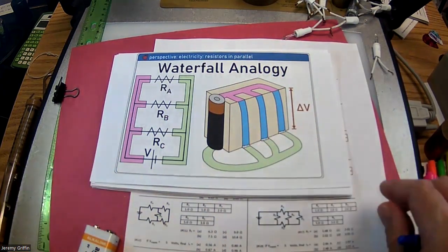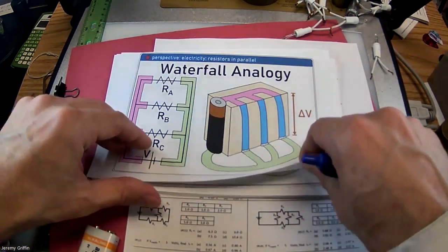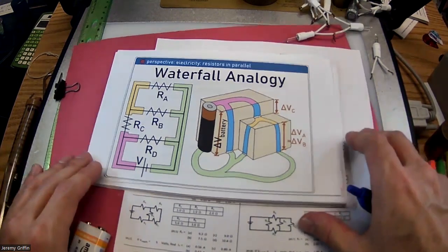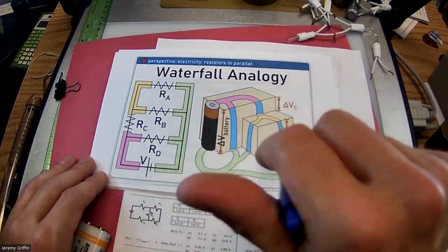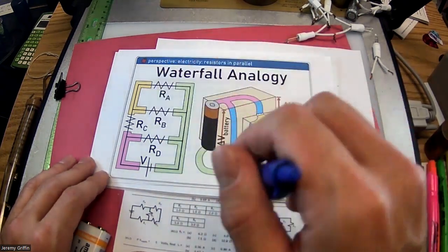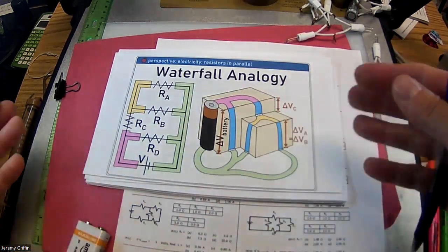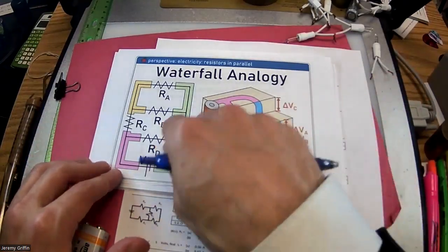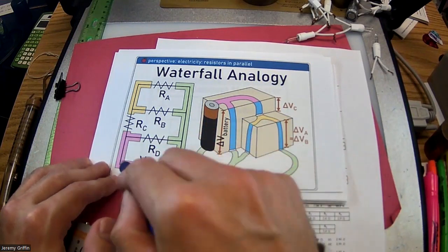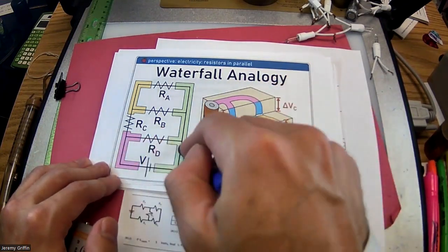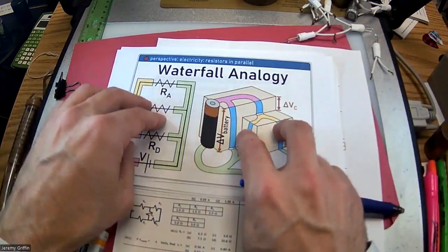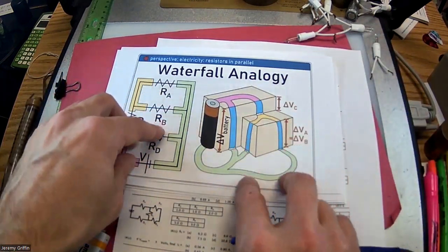So, okay. And you follow those Kirchhoff rules and the things that drop out of those, and figure out exactly how it's going to go. Now, you can get something more complicated. Like what if you had something that looks like this, where there's a combination of series and parallel. Well, now these are getting a bit more complicated, right? So you've got to navigate inside the circuit what's going on. I can tell you guys that this one would be really bright because it's getting the full voltage drop. That's like here, the full voltage drop. And these guys would be dimmer because the current splits and then it splits again, and then it comes back together here at the bottom.